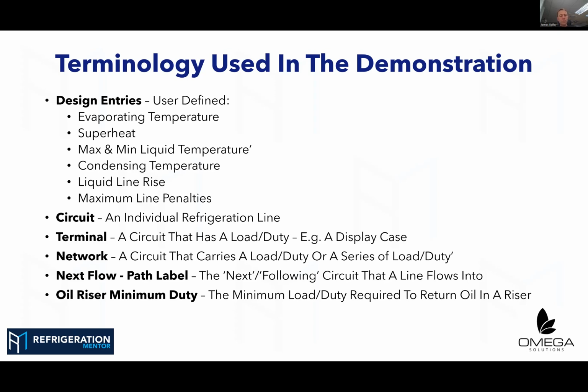Oil risers, wow, what can I say about them? It's so imperative that those are sized correctly, and sized on the minimum duty, to get that oil out of the evaporators, out of that coil, and back where it belongs, at the rack, at the compressor, doing what it should be doing, lubricating and cooling the motor windings down.